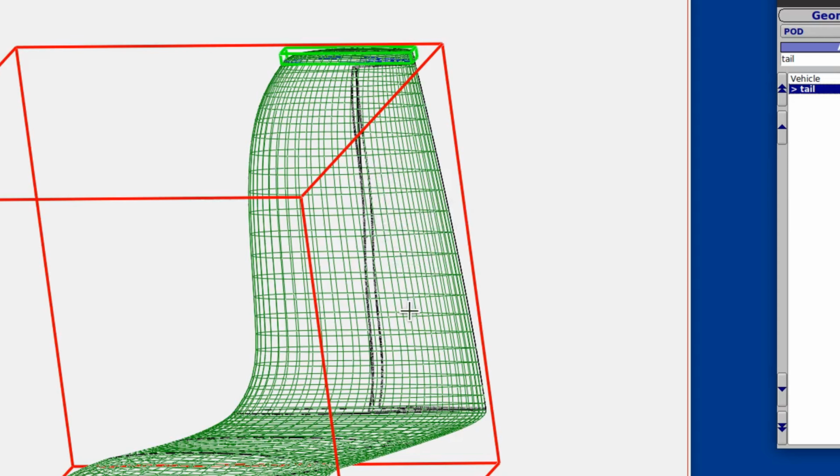So it can twist also. Now that twist will kind of depend on where your control is. If the control is down here at the bottom, then the twist will progress as you go up toward the tip. But if that control is here in the middle, then the twist would progress the same direction as you went down toward the root and out toward the tip.